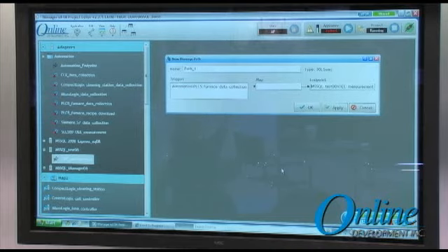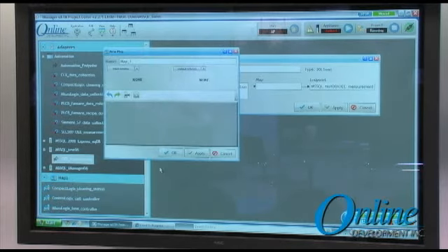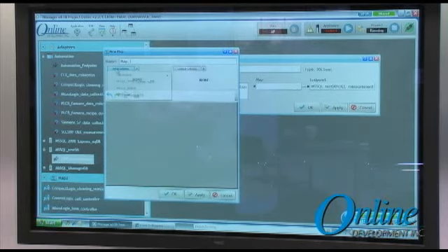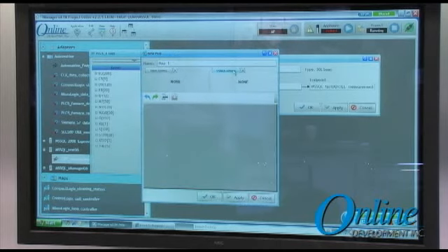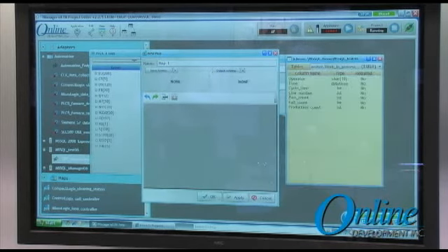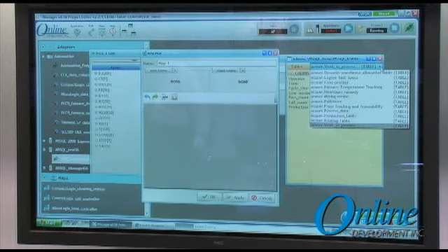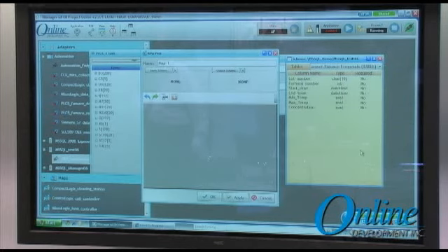And so what we've got now is a trigger occurring in the PLC5, an endpoint in the Microsoft SQL database with properties for store and forward, for failover, for transaction logging. The final piece is the map. So we would need to map the data somehow, and we're going to do that by creating a mapping type function where the input is going to be our PLC5. And so we've got those registers for the input side of our map, and our output of the map is going to be our SQL database. And so we're going to grab a particular table, and remember I told you we're going to use the furnace temperature tracking table, and we'll drag those items over here into our map and link them together.